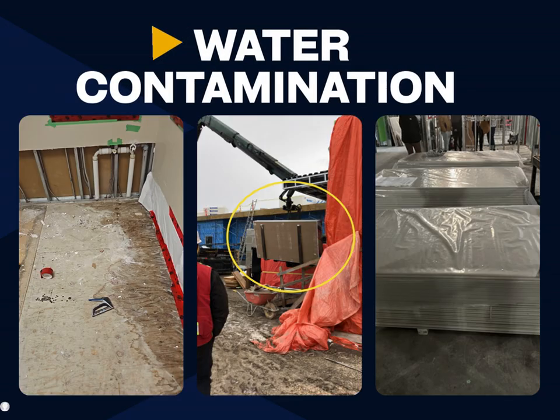Water presents a significant risk during construction, as materials exposed to moisture or dust can become quickly contaminated. Standing or stagnant water, as well as plumbing activities, may release contaminants that can compromise the facility's water supply. Mold is commonly encountered during construction in healthcare settings. Moisture, the primary driver of mold growth, can originate from multiple sources, including plumbing leaks, condensation, flooding, or elevated humidity.